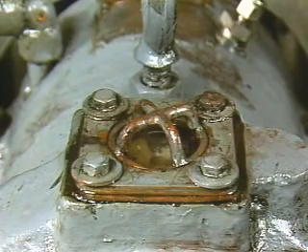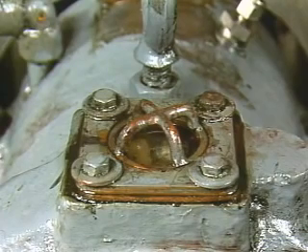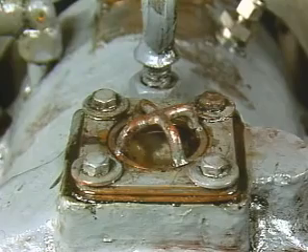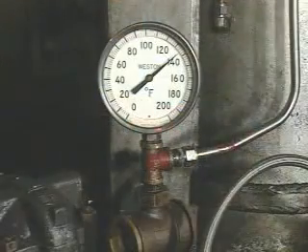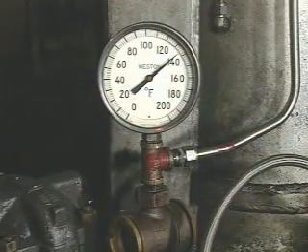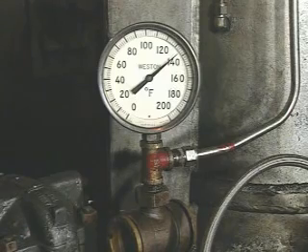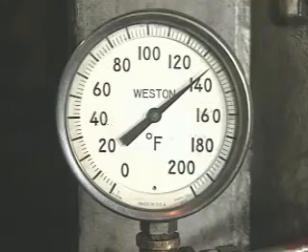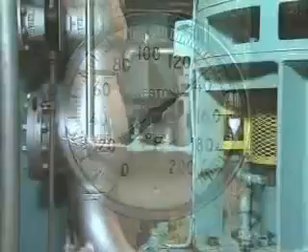If lubricating oil in a sight glass has an unusual color, this could be a sign that the oil has been contaminated and should be replaced. For this pump, a gauge measures the temperature of the lubricating oil leaving the pump's bearings. If the reading isn't within the normal temperature range, there's generally a problem that should be reported.